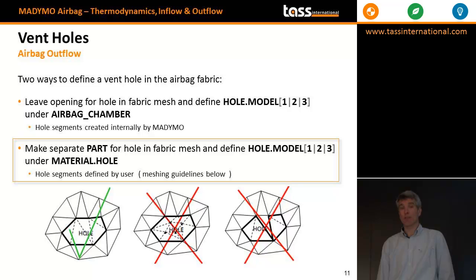As the elements have either no or very low stiffness, you might end up with instabilities. If those nodes are flying far away, you will end up also with a large area of your hole, and due to that the outflow will be wrong.